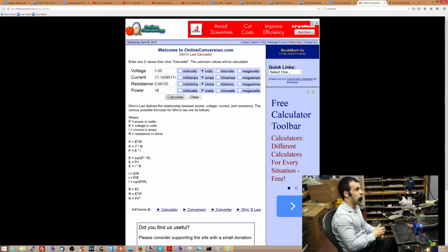So again, this is how, if you have a little bit of electronics knowledge, you can figure out that the CPU is just a really low load. My CPU vCore is not shorted to ground. That is not my problem, and that's it. This is some of the stuff to think about here.